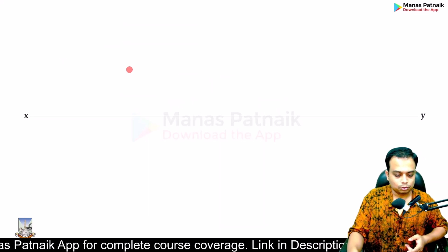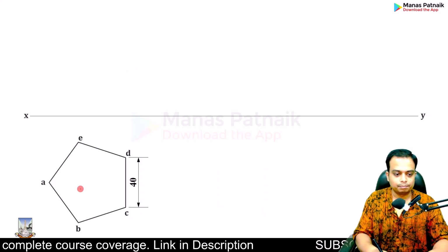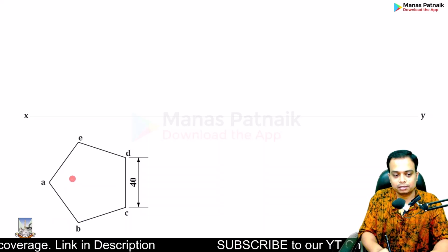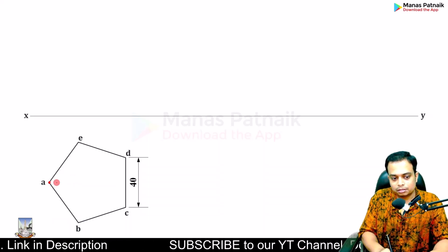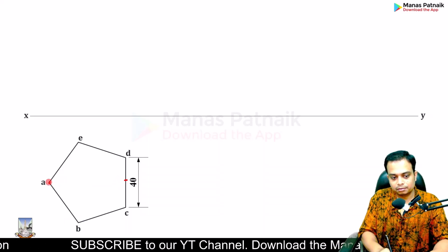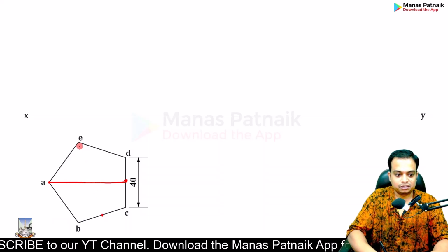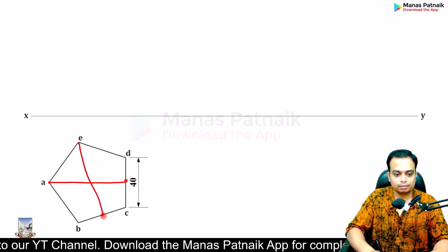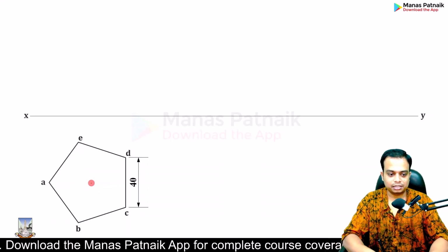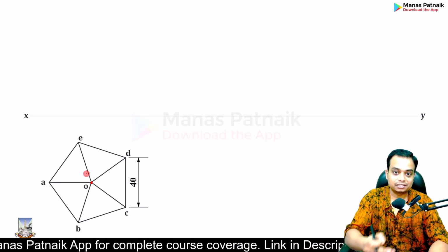Here it is. So first thing is you need to make a pentagon like this. Yes, sir. Done. Where is the center? Sir, center can be found out very easily using intersection of lines. So this is A, and that's the opposite edge. The opposite edge must be having some center. Connect. This is E, and that's the opposite edge. This is BC's center. Join. And these two lines, wherever they intersect, that is the center point. And this center point essentially has to be connected with all of these corners so that they represent the slant edges in the top view.